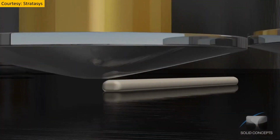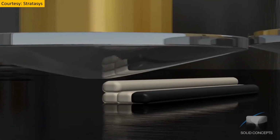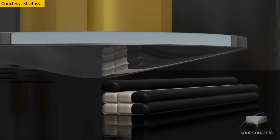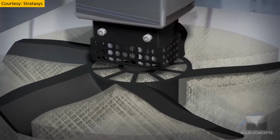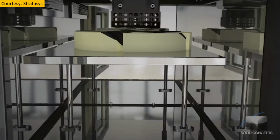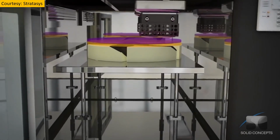The solid portion of the wire acts as a piston and pushes the molten material through the tiny orifice. Of course, wherever required, the support is deposited. Like you can see here, the overhang is supported by the white color support. Also, it can be noticed the support material is of low density, so that we can save material, and also the removal of the support will be easier.